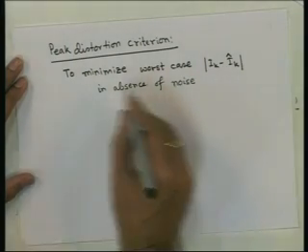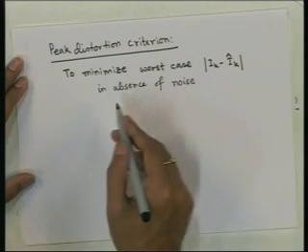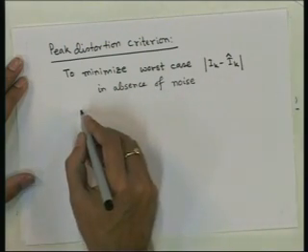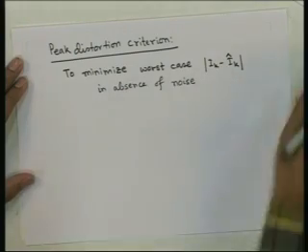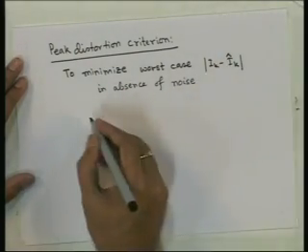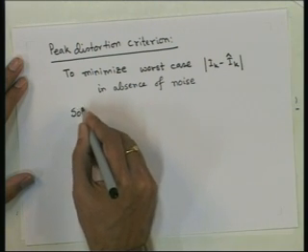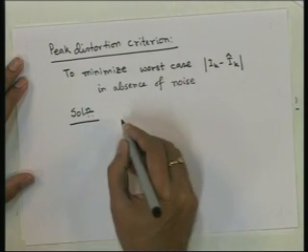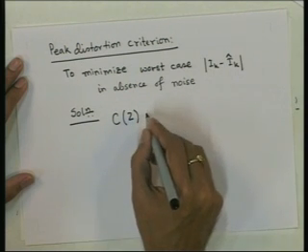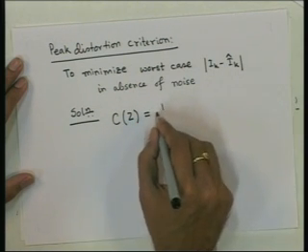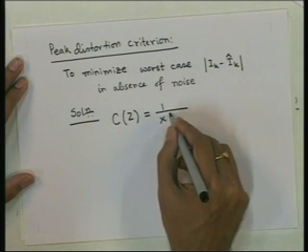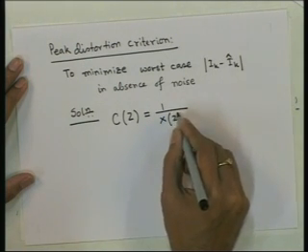So, what is the solution we reach if we take this criterion? It can be shown that the optimum solution for the equalizer filter which minimizes this quantity is that filter whose Z transform is the inverse of the equivalent channel filter.